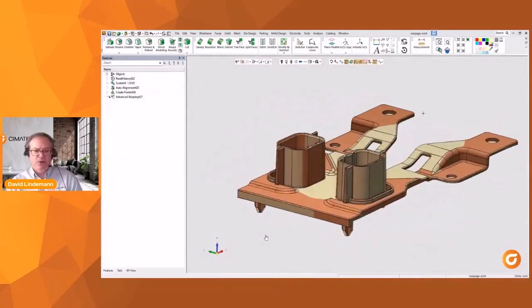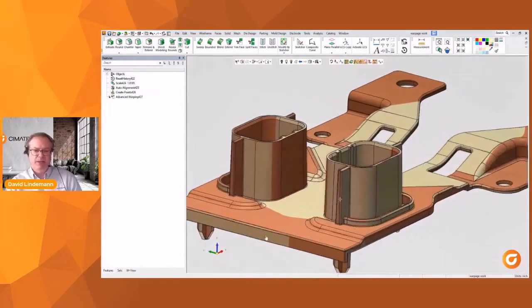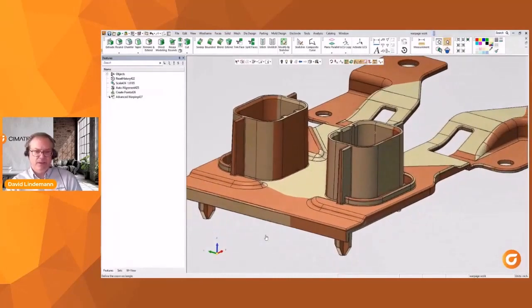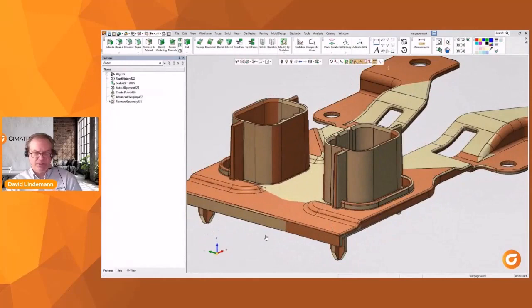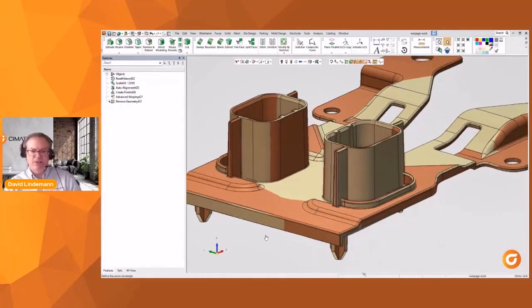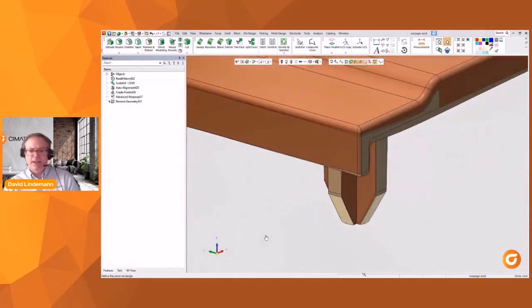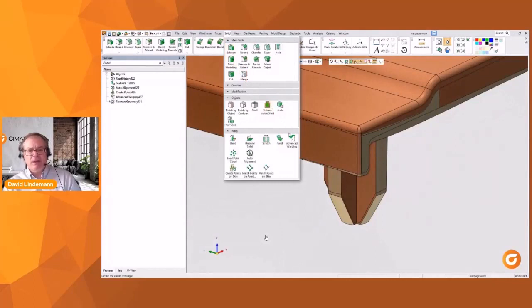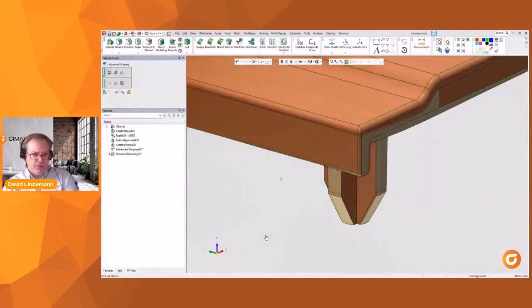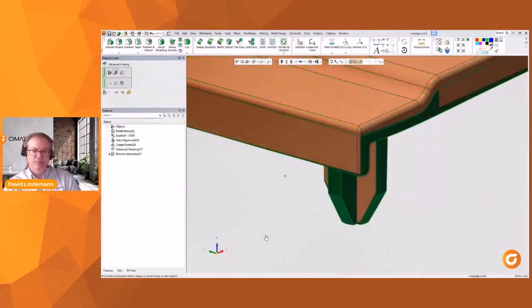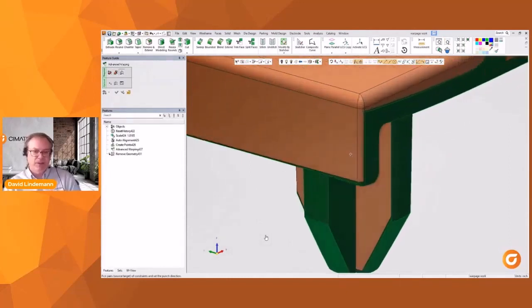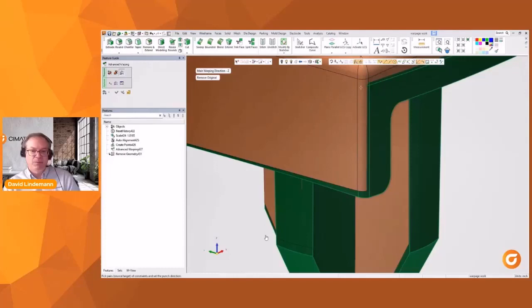Let's say down here in the corner, it's warped considerably, but I need to maintain something right along parting. That's something the customer insists I hold for whatever his design conditions are. And I could see it's slightly out here. So even after having gone through the big version of the software where I point all these points, I can now go back or just simply grab a point on the part and snap it back to the original.